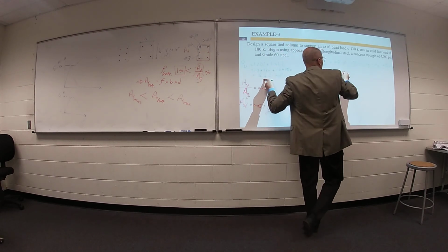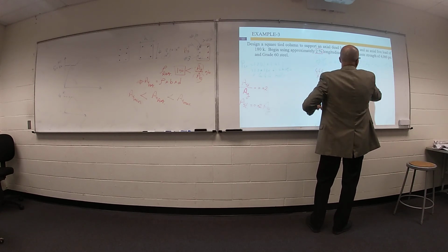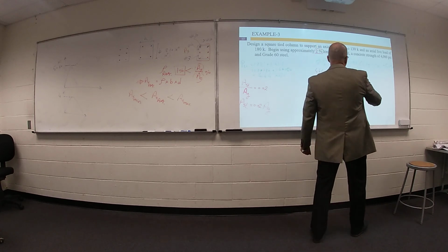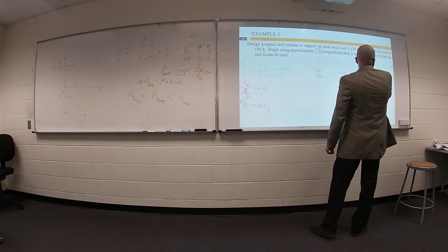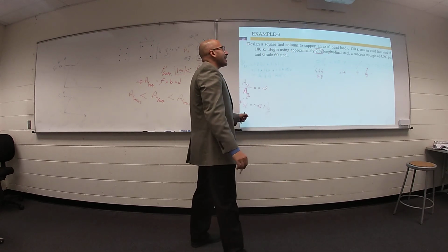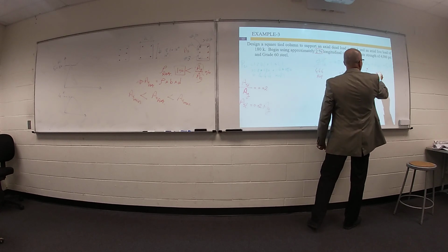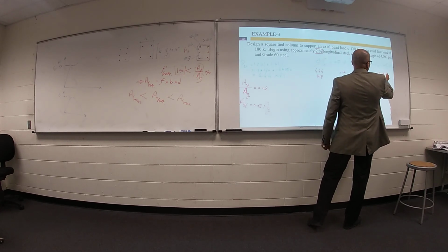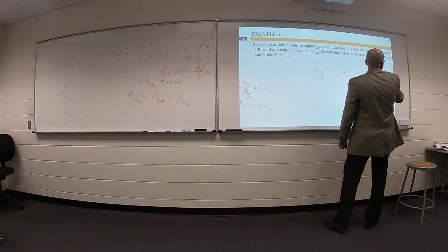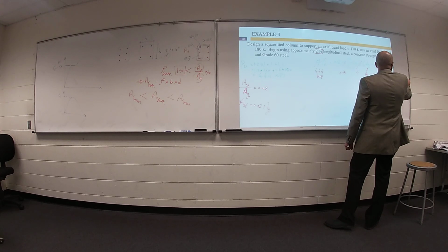Your phi is 0.65. F'c in kips will be 4 ksi. Area gross, I don't know what the area gross is. Area steel, I will remove and put 0.02 area gross, plus F yield 60 times area steel, 0.02 area gross.